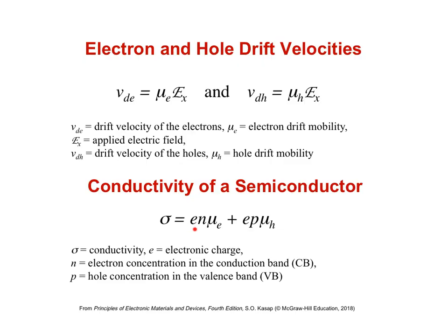We think of electrons and holes as transporting charge independently and parallel with one another, so that the total conductivity of a semiconductor can be thought of as the sum of the contribution of the conductivity of electrons and that of holes. We often reserve N for the electron concentration of the conduction band and then use P for the hole concentration in the valence band.